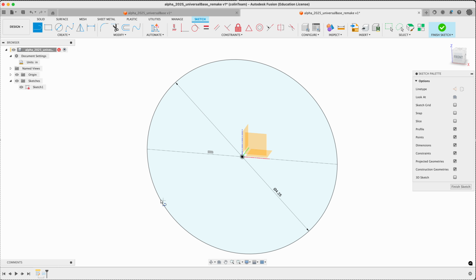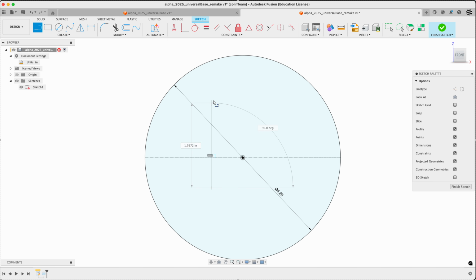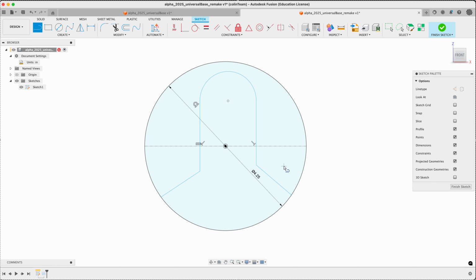So let's do that. Just going to get started. I'll sketch it in a kind of rational way here, starting out here just to get our setup going. And I can almost start doing some lines over here. Once you hit a hard stop like this fully defined circle, it'll stop the line tool, deactivating the polyline and letting you draw some more.